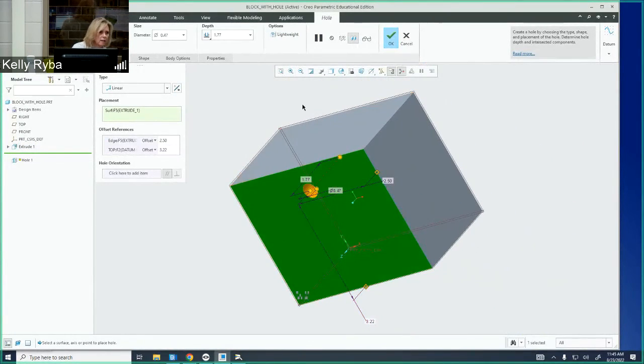Position here that this hourglass on the left-hand side will always fit it to the screen for you if you find you need it. Double click on that dimension, and that is 1.5, and then enter. Okay, so locationally, I have my hole where I need to be. I think this hole wizard works way better than SolidWorks, honestly. For some reason, the hole wizard is annoying to me in SolidWorks, but this one works better.